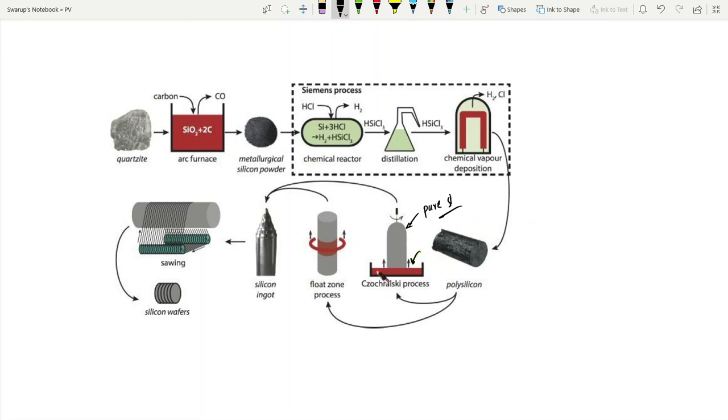So while growing itself, we add p-type impurity to it, right? p-type is like trivalent atoms, so we drop them in this molten silicon. We add those trivalent atoms here itself. Okay, so whatever is grown for the application of solar cell, while growing itself, we grow it as p-type crystalline silicon. We write it as c-Si, meaning crystalline silicon. So after sawing, this wafer is already p-type.